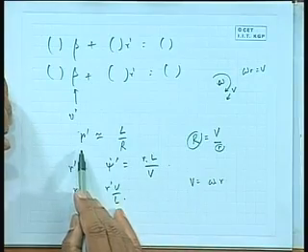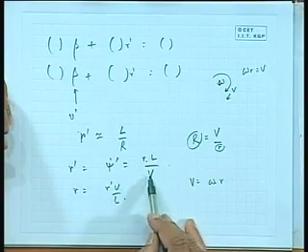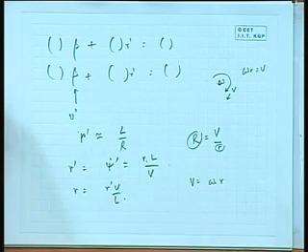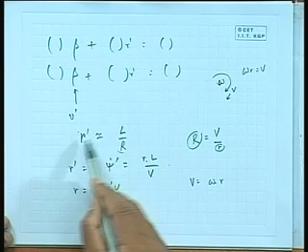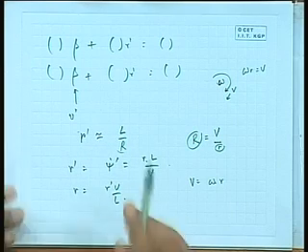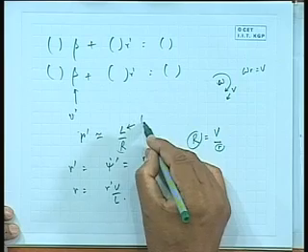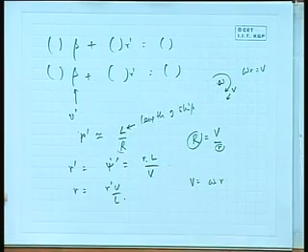All I want to tell you is that if you use this kind of thing, you will find out that r dash, which is by definition r L by V, will turn out to be L by R. In other words, basically this R term comes in. The non-dimensional yaw velocity is L by R. L is the length of the ship, R is the turning radius.